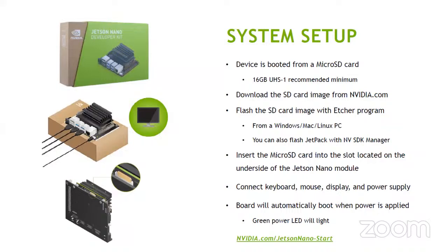NVIDIA itself provides SD card images, meaning operating system images for Jetson Nano. The OS is called Jetpack. You can download that for free from the NVIDIA website, and then write that OS to a micro SD card.